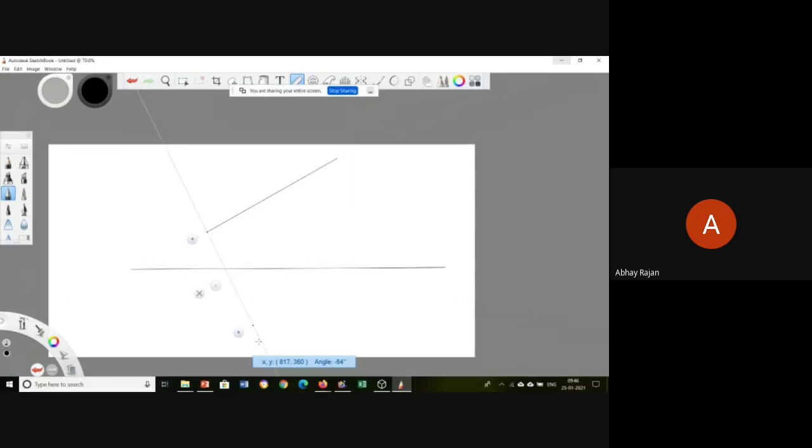So you'll be drawing the projector lines downwards, and make sure that these lines are thin lines. Okay, so since I am drawing here, I am taking the same things, but don't do that. What you have to do is, whenever you are drawing, apply a slight pressure so that the lines will be thin lines. Okay, only thick lines are required for the projections only.